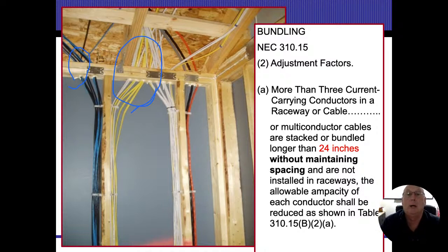Now the bundling talks about the amount of cables that are allowed to go through that opening that's on there. Now I get it. The wires on the left-hand side are cable and data. I'm all over that, you know. But even though we still want to have those wires protected. However, the yellow wires going up there and the white wires, those are not. All right, those are non-metallic electric. The bundling of the wires, as we're seeing, kind of loose in there, going down the studs.